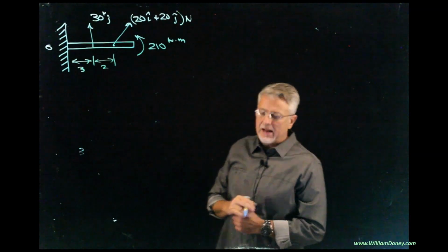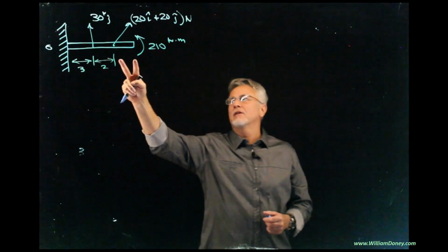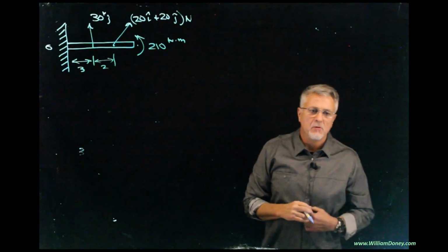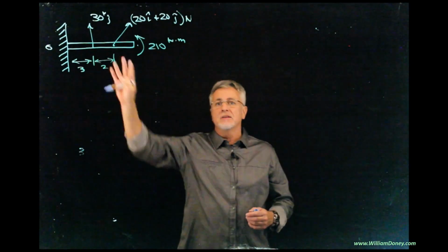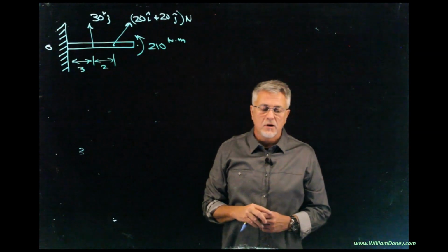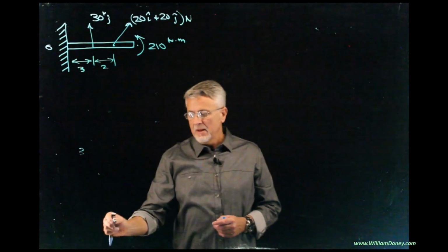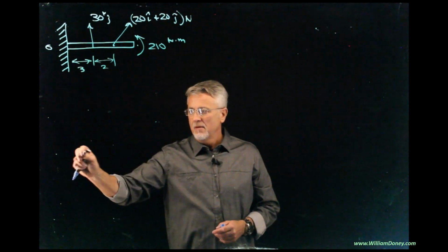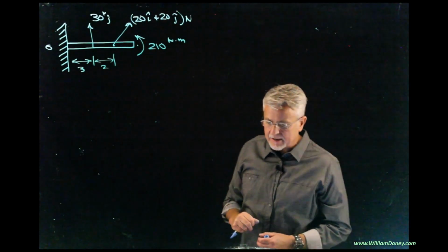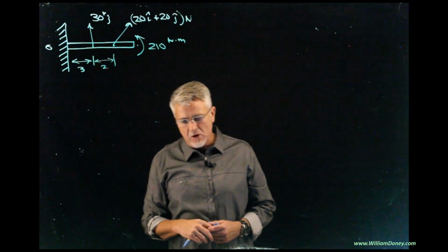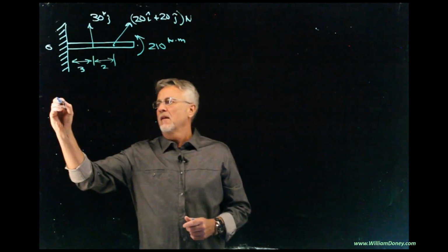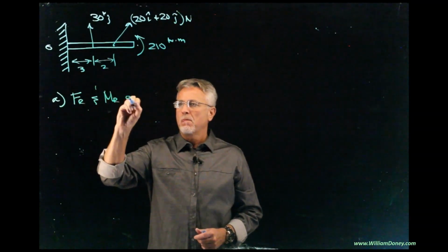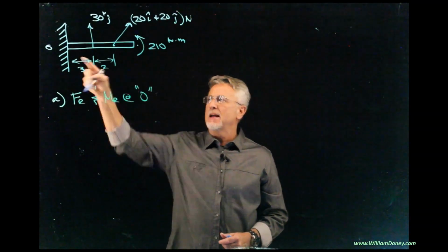Not really concerned about the additional length here because I don't know how many forces are acting. That's a couple moment. Again, couple moments are free vectors. We can slide those anywhere we want. So we're not concerned about them as far as needing a distance there. All right, so we're asked to find the single resultant force and moment acting at O. And O again being the origin.